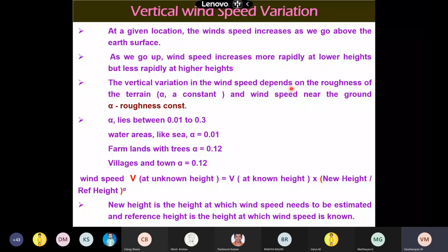In water areas like the sea, alpha would be 0.01. In farmlands with trees, alpha is equal to 0.12. In villages and towns also it seems 0.12, and we can calculate the wind speed at an unknown height as equal to v at the known height, the velocity at the known height, and...